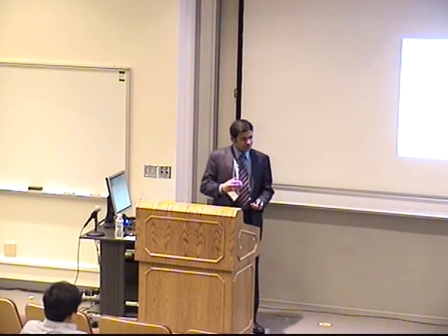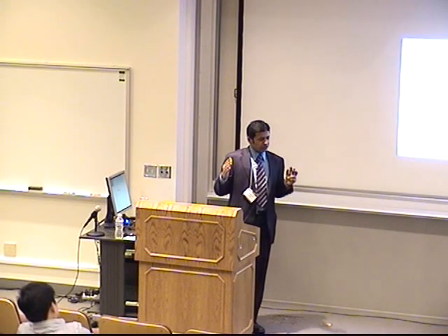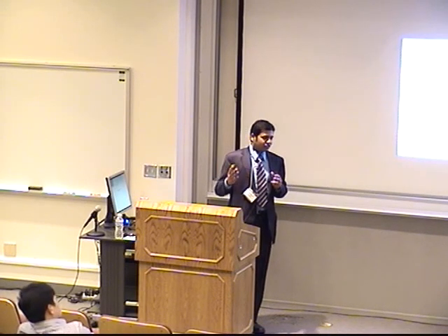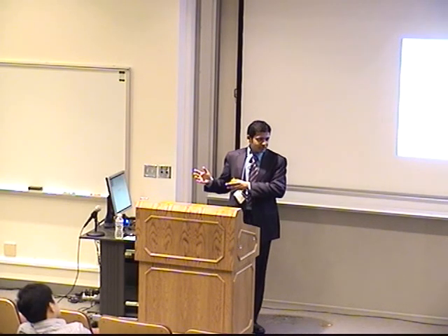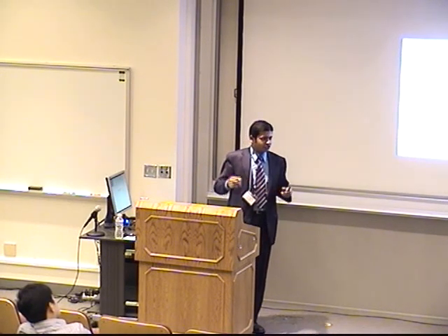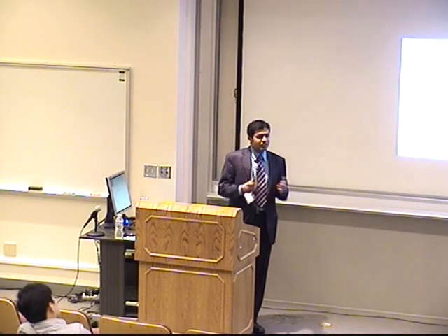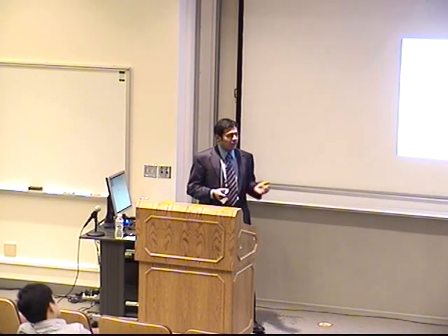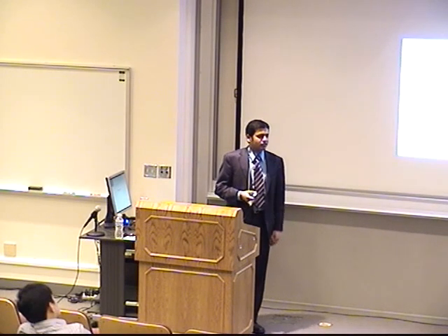The control approach that we use, that's a question that's more relevant to the control part. We capture all this in an objective function, and then change the weights. There's a term for the comfort, there's a term for the energy, there's a term for robustness. So all these various things that you would like to achieve, you can model that in a cost function, and then design your controllers based on that. But we need a model for that. That's the important thing, and we need a simple enough model, and that's the first step that I presented in this work.